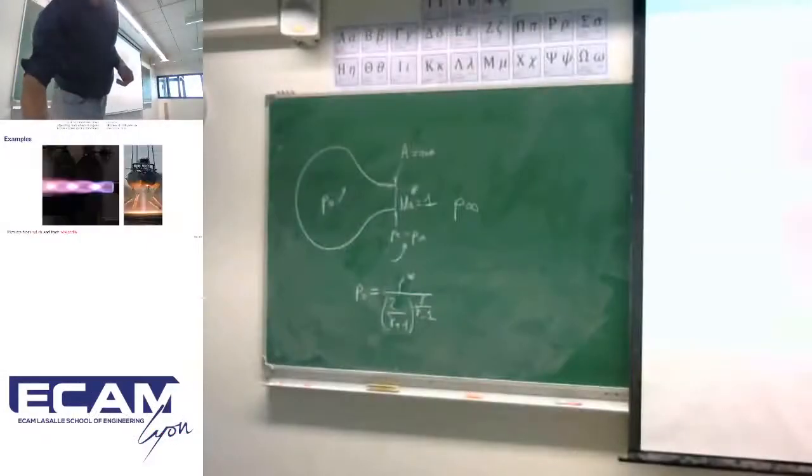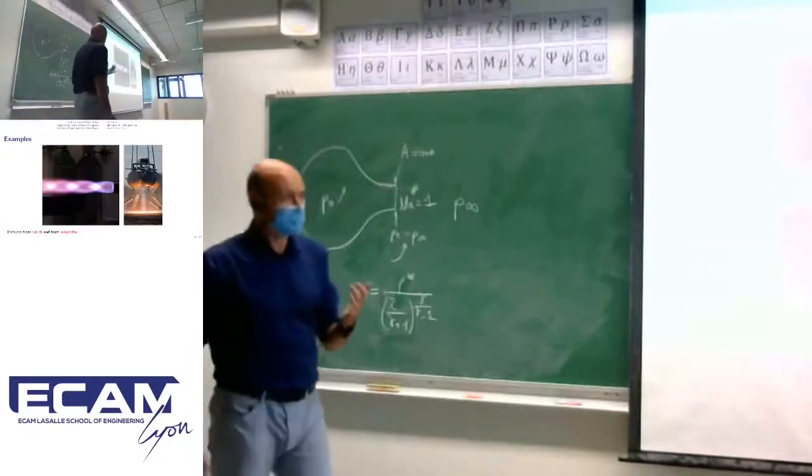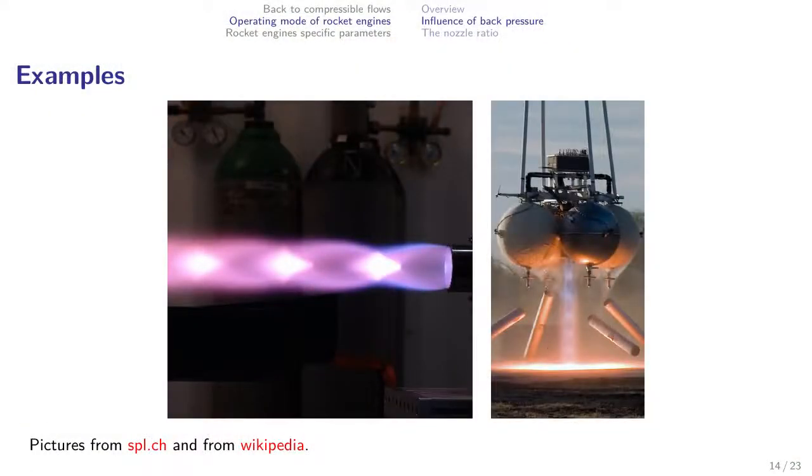And if I take a look at some practical examples, I obtain exactly that. These are examples of diamond shock waves at the outlet of some thrusters. This one corresponds exactly to this kind of situation where the exit pressure is higher than the ambient one, and so the only possibility for the gas to equilibrate its pressure is to create this kind of diamond. It's not exactly the diamond I drew because I have some gradient of chemical composition, but it's exactly this structure. In each of these locations, I have a different value of pressure until I reach equilibrium at the end. So it's a typical effect.